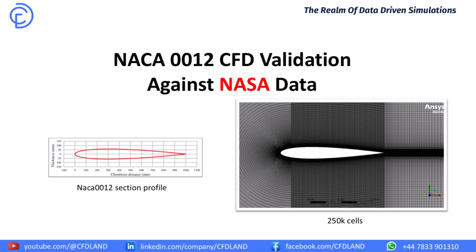So if you're interested in this field, you surely need to learn how to do a structured grid over an airfoil in the first step, and then you can get through the other applications. By the way, this study is going to employ a blocking technique, which gives us the chance to generate a structured grid with only 250,000 cells. So if you're a student or you're using a student version of ANSYS without any limitations, you can perform this simulation.